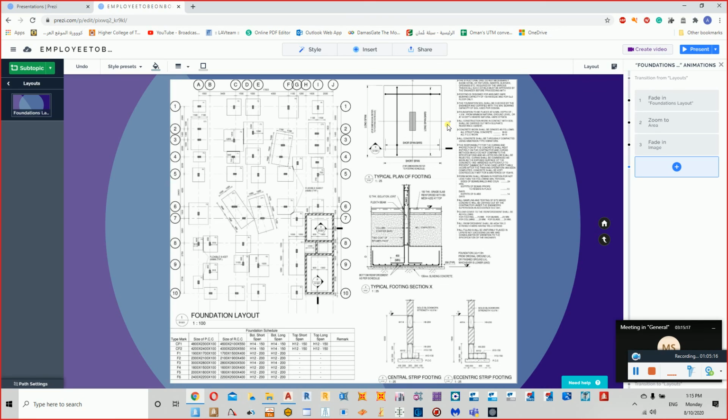We need to know the different components. For the beams, we learned that we have plinth beam, cantilever beam, and hidden beam as well, in regular drawings. And for the slab, we should know what a sunken slab is, where it is, and how to find it in the drawing. We should know how to read the reinforcement, and I explained the meaning of main bar, extra bar for the bottom, extra bar for the support, for the columns how to read it, and whether we can change the cross section for the same column or not. Then we discussed the links for the beams, the number of legs and how it affects things, and finally we ended up with the foundation.